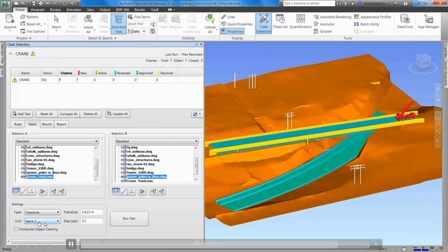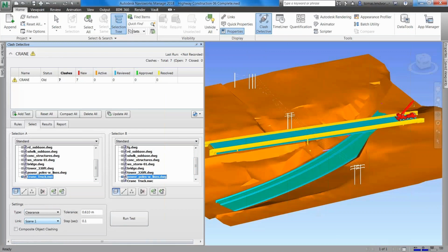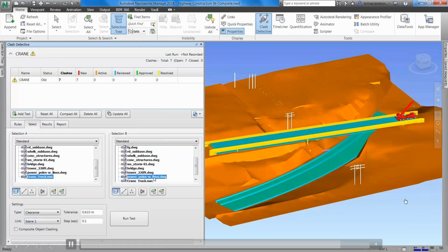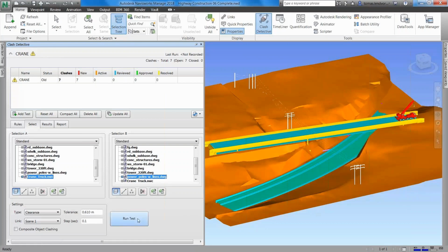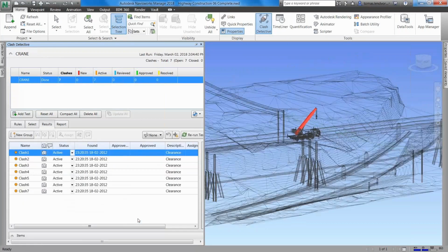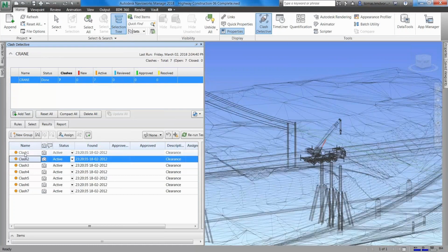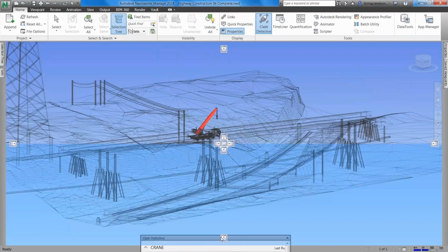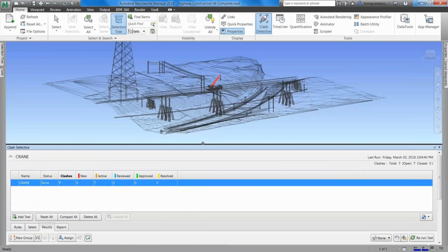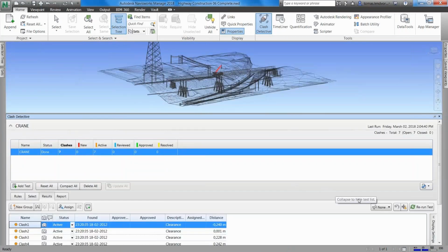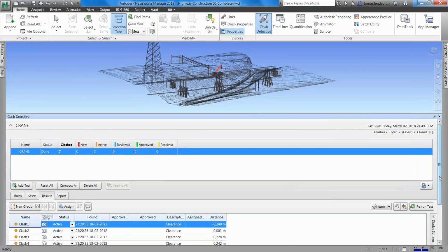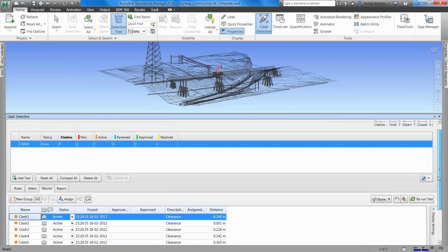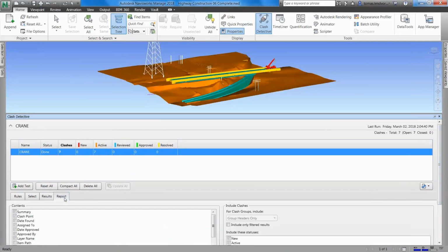moving. So you can see this is assigned to the scene. So it's not a static object, it's an animated, moving object. And now I will say, okay, interrogate whether this animated object will clash with these overhead electrical lines. And obviously there will be a clash, so I see that it would be very dangerous for this guy sitting in the crane and working there. So I have to make some decision, if maybe these lines will be cut for the time being, or there will be some different solutions.